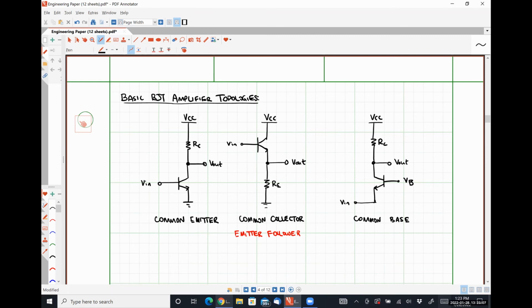Voltage gain is fairly straightforward. We know that that is simply the ratio of the output voltage to the input voltage. I believe we've beaten that to death in multiple other classes. Okay? We will go through the steps of doing it, but I don't feel that I need to explain that quantity. Measuring the input resistance and measuring the output resistance of the amplifier might not be something that you're used to doing. You're probably used to having it told to you. Okay. So let's talk about what those steps entail.